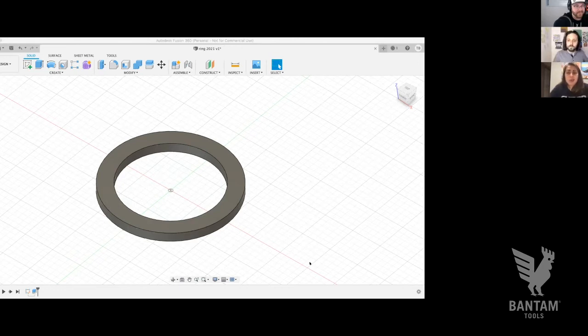Taking into account the thickness of your stock when you're designing in CAD can help you later down the road when you're programming your CAM. Because when you program your CAM, and we're going to talk more about this shortly, during your setup you're going to have to input those dimensions. And I can't tell you, especially when I first started, how often I would design the thing.